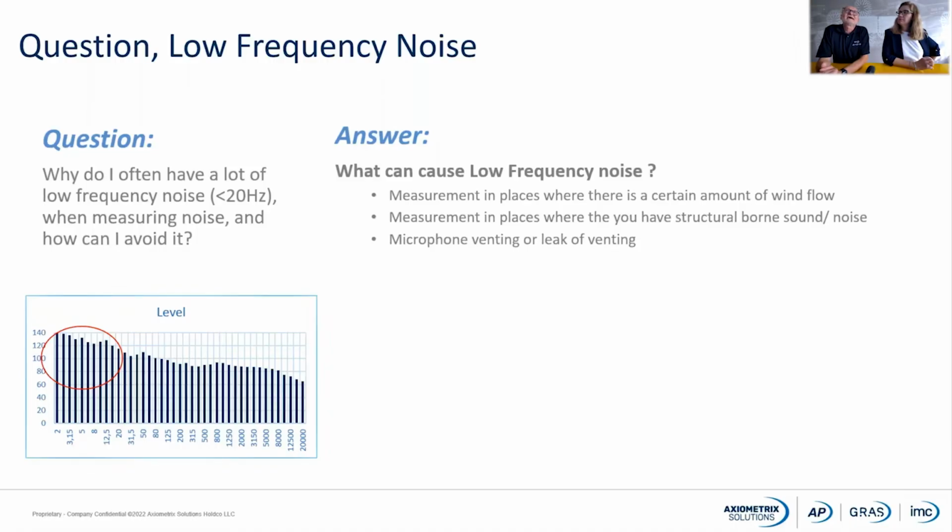First of all, what can actually cause low frequency noise? Maybe you are doing measurements in a place where there is a certain amount of wind flow. Maybe you are doing the measurement outside, or you are doing it in a place where you have structure-borne sound noise.